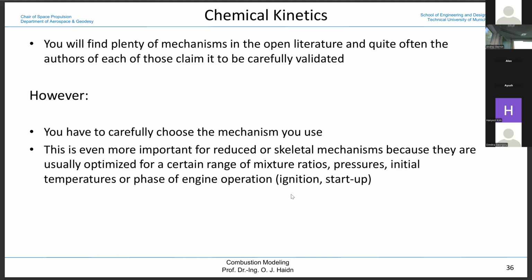Flamelet also quite often uses some kind of progress variable in order to take into account local progress, in terms of how fast the reaction is progressing. So there is some kind of workaround for cases where classical flamelet equilibrium doesn't work. But that's a bit much.